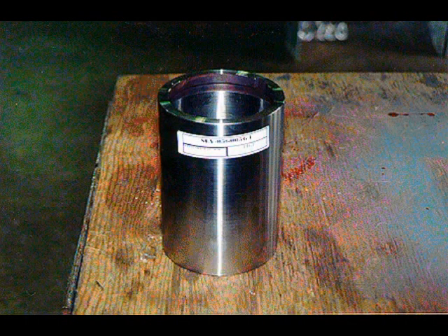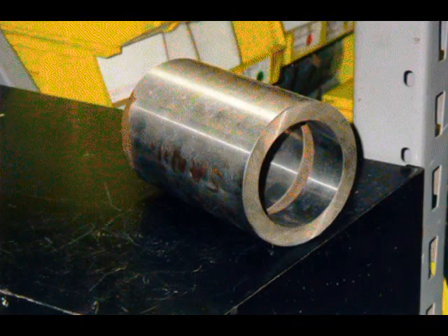They must fit tightly on the shaft so that the sleeve does not turn, and so there is no leakage between the shaft and the shaft sleeve. Sometimes an O-ring is also used to reduce leakage. Both the removal of the shaft sleeve and the installation or pressing on of a new shaft sleeve will have to be done in a machine shop. Note, too, that any O-ring should be replaced when the shaft sleeve is replaced.